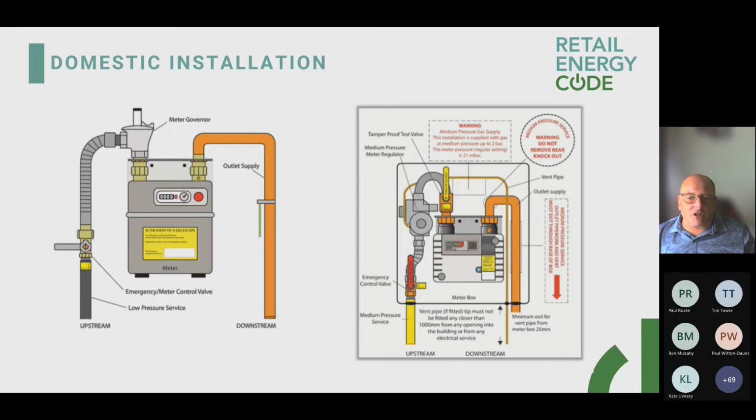For a 5-yearly visual inspection, they'll still have to go inside and inspect the flame and make sure it's burning correctly and the working pressure. For the 10-year, it's a test on the slam shut and that the regulator is still working properly. So they have to repeat that process. But it gives you a differentiation between the two and what the two are in effect there for.